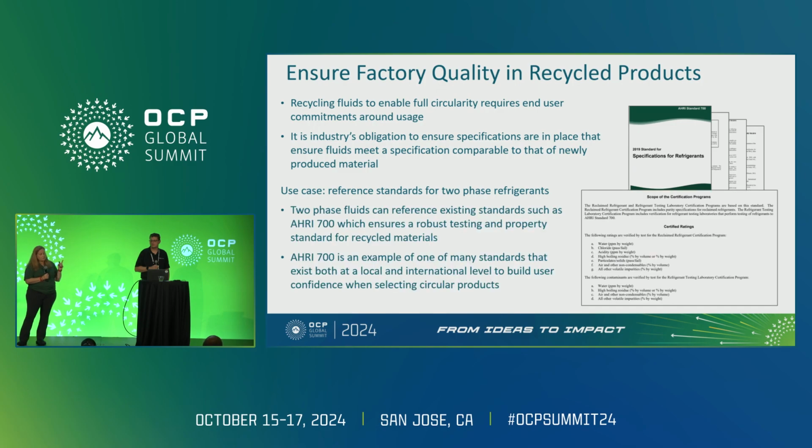We can borrow a lot from the two-phase refrigerant technology because they have established standards, and we can create similar expectations of recycled and reconditioned fluids for immersion cooling applications, to ensure that the silicon manufacturers and the server makers will be able to warrant a system that is immersed in a recycled or reconditioned fluid.